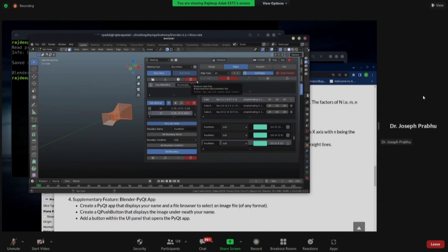What Build Mesh does is get that information out of another source file and convert it into a proper OpenFOAM interactable dictionary. So that's why we have a separate option called Build Mesh. Okay, got it. We can model it, but meshing we can't do here. Yeah, you can model it and create the blockMesh dictionary, but not the mesh information. So it's not a mesh generation software. It's rather mesh defining software.